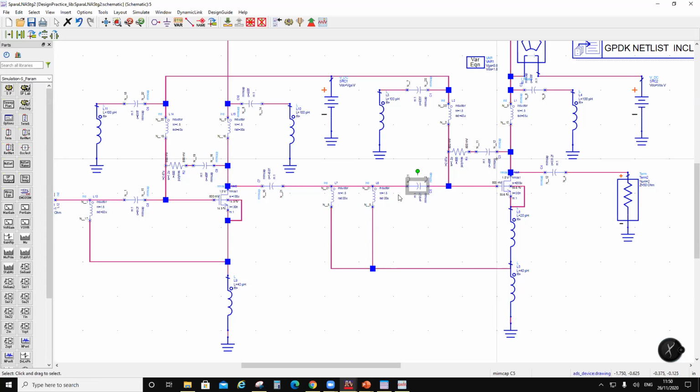Now you have two inductors. Now these two inductors, of course, you cannot replace them. Well, you can replace them with one inductor. The reason for putting two inductors was that the process didn't allow me an inductor with a radius less than 20. So in this case, in a real circuit, I'll just put a trace of line going to ground. That's it. And that would be done. So this interstage doesn't need any simplification.